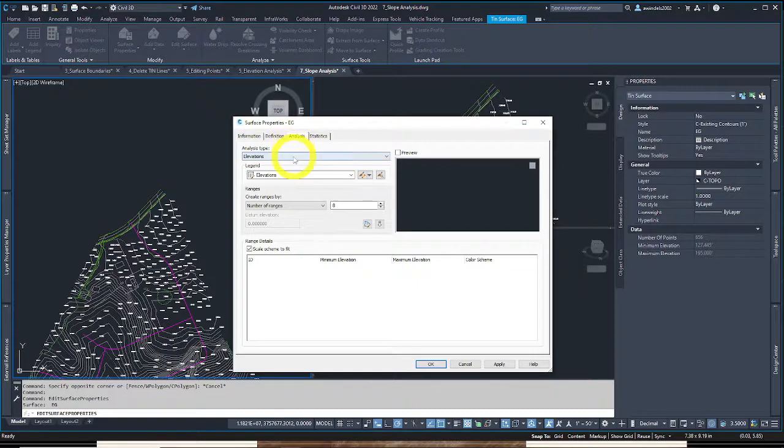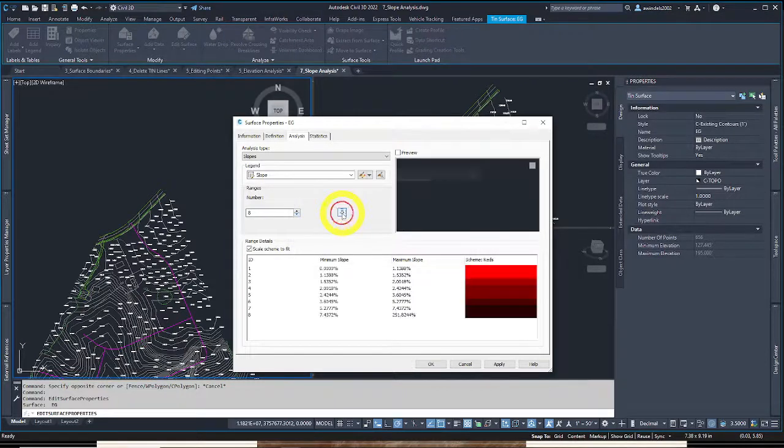And we're going to change the analysis type, of course, slopes here. And we're going to click the downward pointing arrow. It doesn't say anything about changing anything, so we're just going to keep the 8 ranges. And here's our mathematical judging on the surface statistics. Any surface could be different in this regard. It puts 8 quick ranges. This is kind of bogus and crazy, but in general, anything above 7.5% slope is this really dark amber, the inferno of Dante right here. So we'll hit OK.